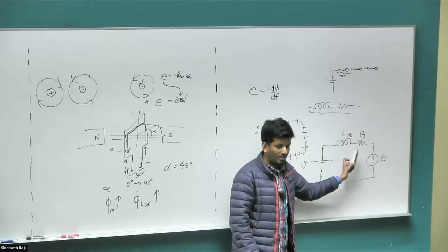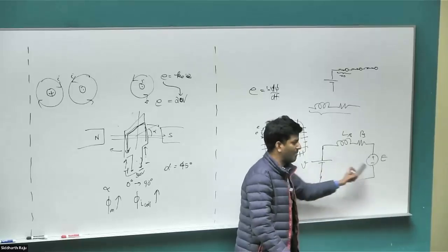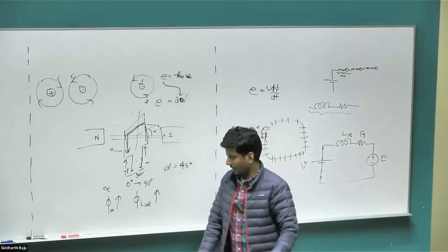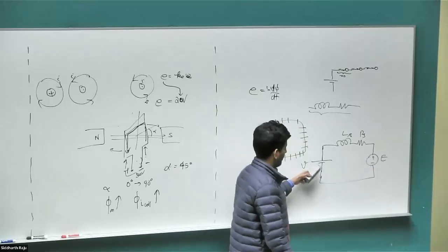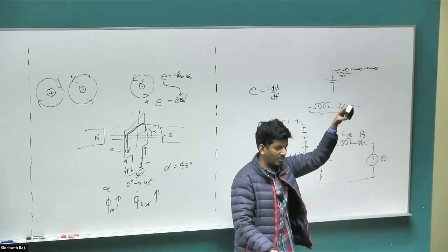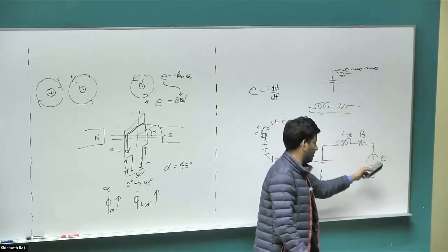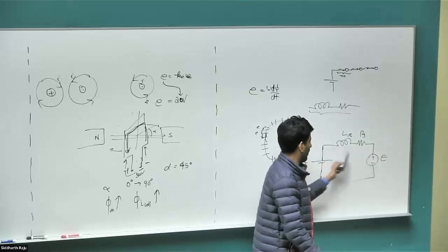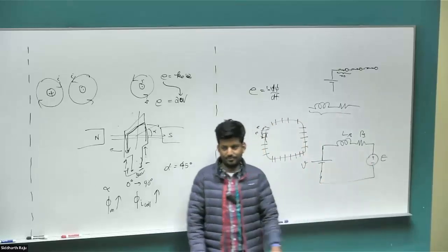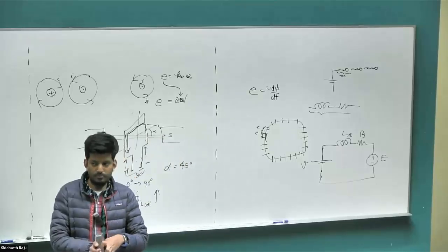It gets bigger until the point where they balance out. It will reach a steady state. So you apply a larger voltage. That's the reason why the motor accelerated every time we step the voltage. It's because of this difference. Current increases, torque increases, speed increases, EMF increases until they reach a steady state point. Okay. Any other questions?